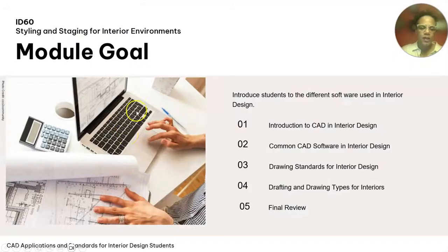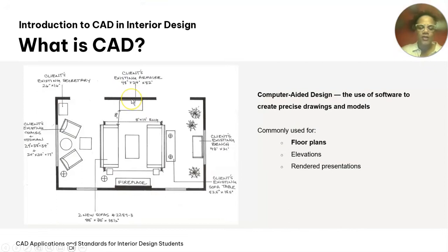So these black thick lines are basically the thickness of my wall. And then I have 2 openings here that don't have any doors, so I can just walk back and forth. Then I have this opening in the wall, which is a window. And I know that because there's a line that goes through it that represents the glass that happens in a window. And then this is the exterior sill of the window where the pigeons sit, and then the interior. So I have window, wall, window. I have a fireplace that happens here, and I know it because of the drawing, but also because it's labeled. And then I have window, window, and another opening.